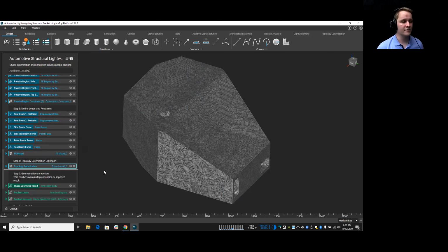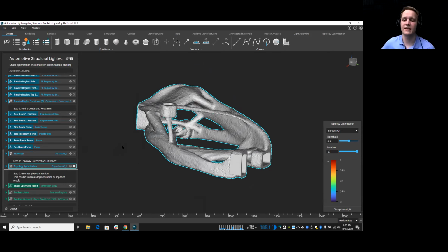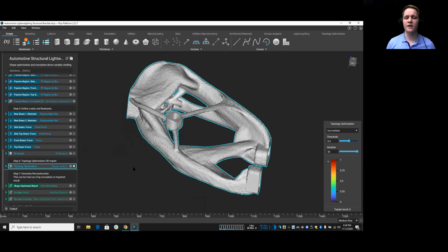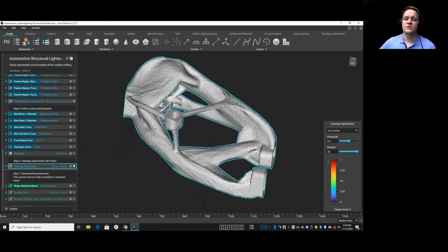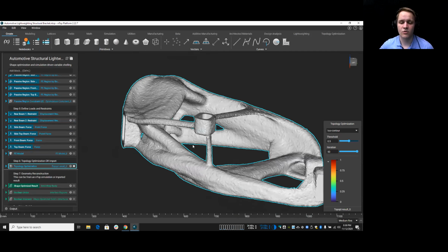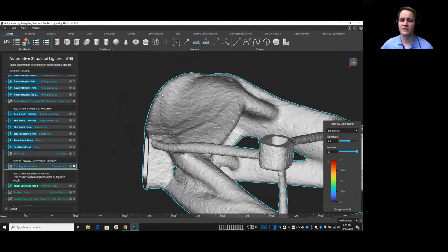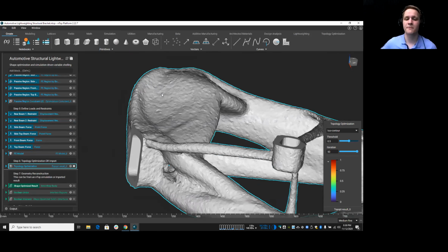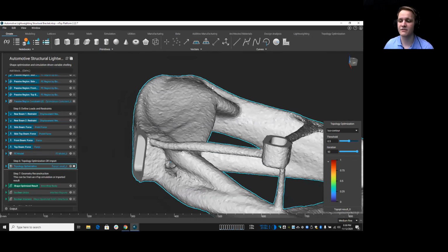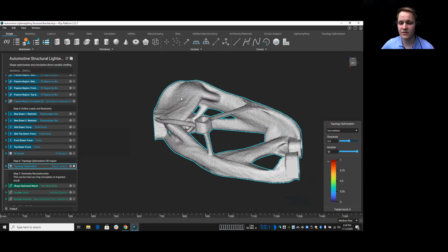The hard part starts once you have this initial design. So you go through that process, you mesh it, you put all the boundary conditions on, you say, okay, optimize my geometry. You get this sort of result here, and this result has a couple issues. The biggest issue is the surface. Because it's computed from a mesh, it's tessellated everywhere, and it's very coarse. It has lots of stress concentrations. In short, it is entirely unusable. You can't use this as is. So we need to do some work.